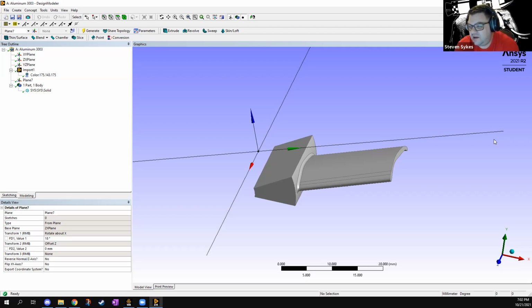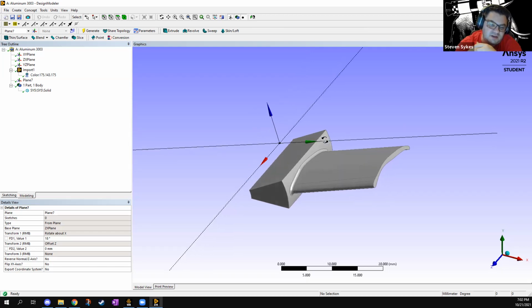Okay. And then I thought about potentially a bird strike or some type of thing like that. Your isolated circle or geometric shape on top of the fin kind of works to simulate that impact strike. Now, it's sort of an instantaneous thing, so we'd be analyzing the stress as the bird struck, not over time. Right. Yes, so it'd be a static simulation, basically the instant of impact. Okay, good. Yeah, I think that's all.